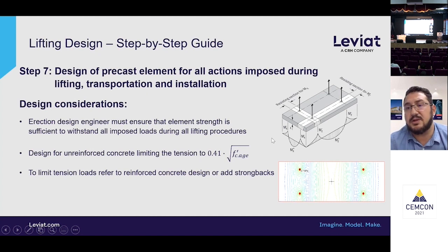One more thing is that when you're looking at plate-like elements particularly, they're generally not designed to carry their self-weight because they're designed as vertical elements. And so an additional check needs to be made to ensure that the element itself is not going to crack during transportation due to its self-weight.